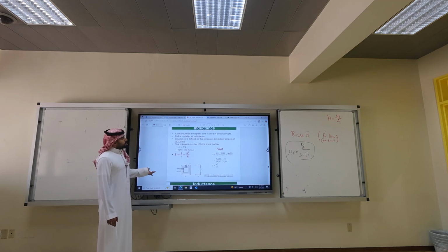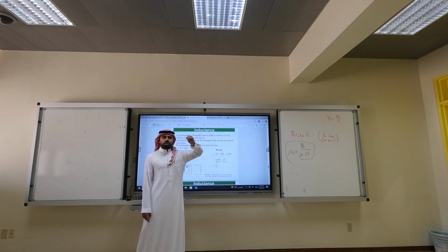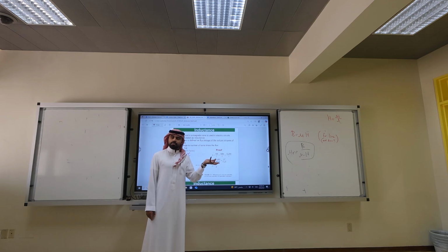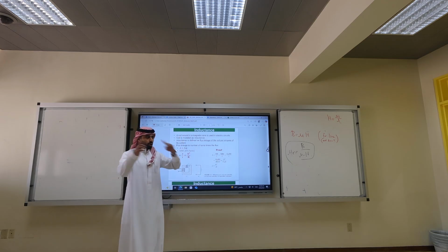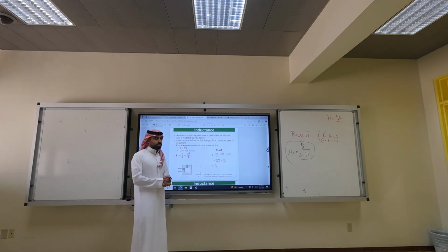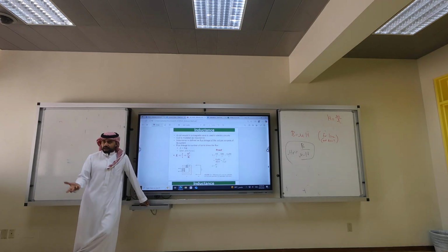Now, you are familiar with an inductor, right? And we told you the inductor stores a magnetic field. So is the coil that's wrapped around a core, does it resemble an inductor? Yes, because you're holding the magnetic field in the core. So it is similar to the inductor. The inductance, is it an intrinsic feature of the device or does it have to do with the supply? Like resistance, it has to do with the geometry, material, etc.